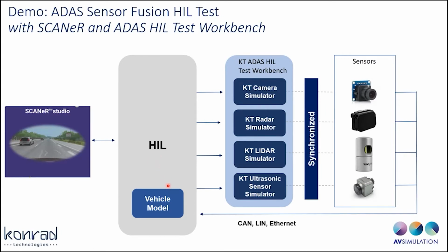And this hardware in the loop platform, and there could be a variety of different real-time platforms that perform this operation, can then connect to what we call the Konrad Technologies ADAS HiL Test Workbench. Now, this workbench combines several separate systems that function as simulator systems that can be connected into a single workbench. So we've got a simulator for camera, radar, LiDAR, and ultrasonic sensors.